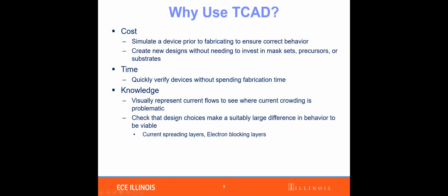So why are we using TCAD simulation? There are a lot of reasons, but basically we are trying to reduce the cost to design a device or to study a device, because typically fabricating a device in a clean room will take more than 4 months from design to measurement. And also the knowledge.